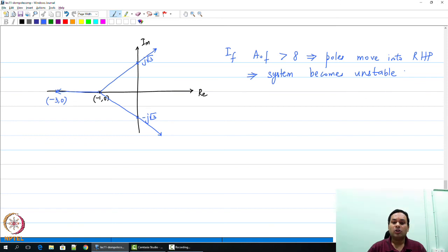So now you may notice that we had actually seen the first order system is unconditionally stable, the second order system is stable, but when you try to achieve large loop gains, the system has very high quality factor or very low damping factor, and the closed loop response, even though unconditionally stable, can have a lot of ringing.